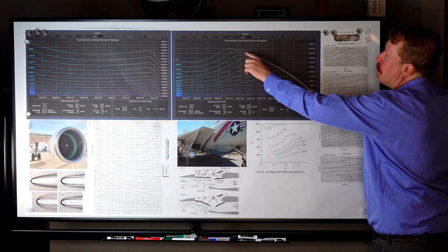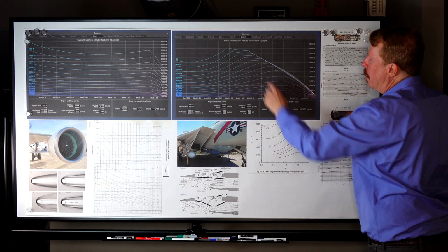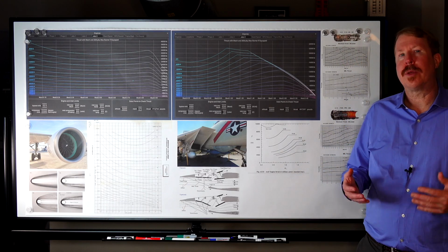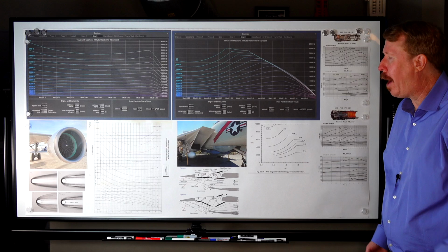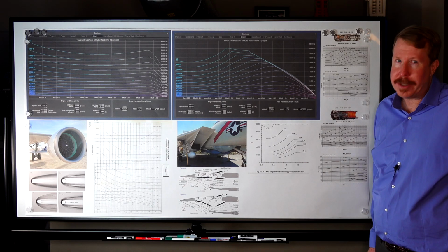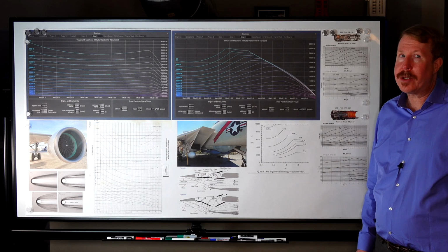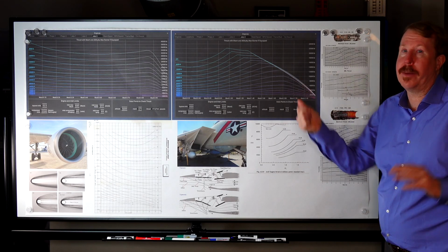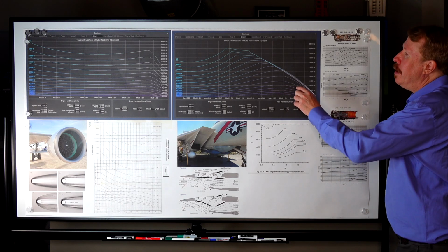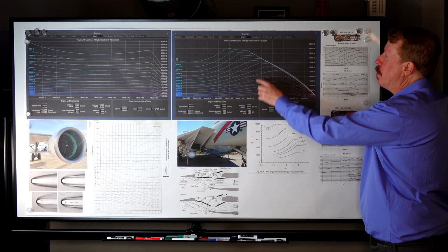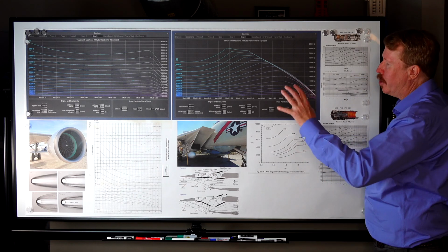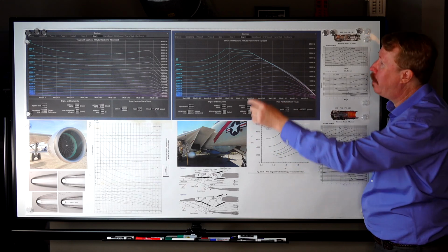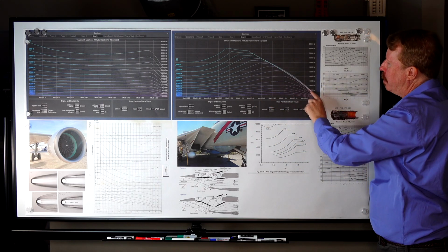Now, this is really nice and all to hold a nice constant thrust and a nice constant pressure, but at some point, the temperature builds up. Temperature goes with Mach number squared, and so I don't care if you're high, low, or anywhere else, it makes no difference. Once you get to a certain Mach number, you're at a temperature that's going to be elevated, and that temperature, again, elevates with Mach squared. So once you get to, in this case, 120 degrees Celsius of compressed air temperature in the inlet, you gotta back off again to keep from over-temping anything. And so there's your next limit, temperature.